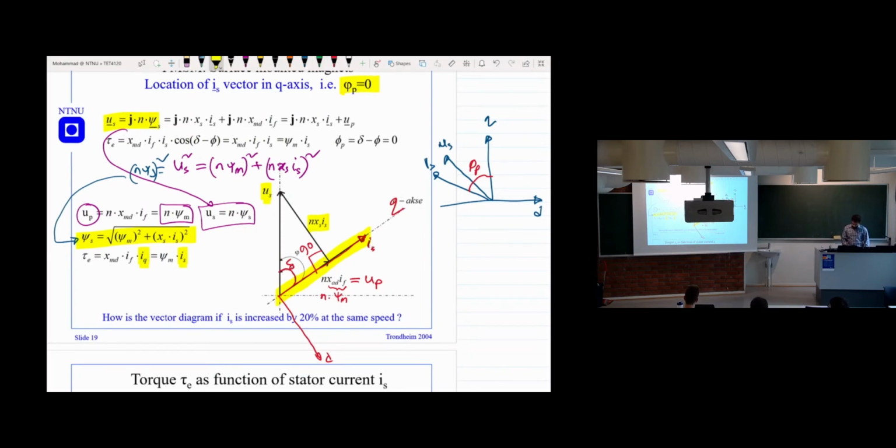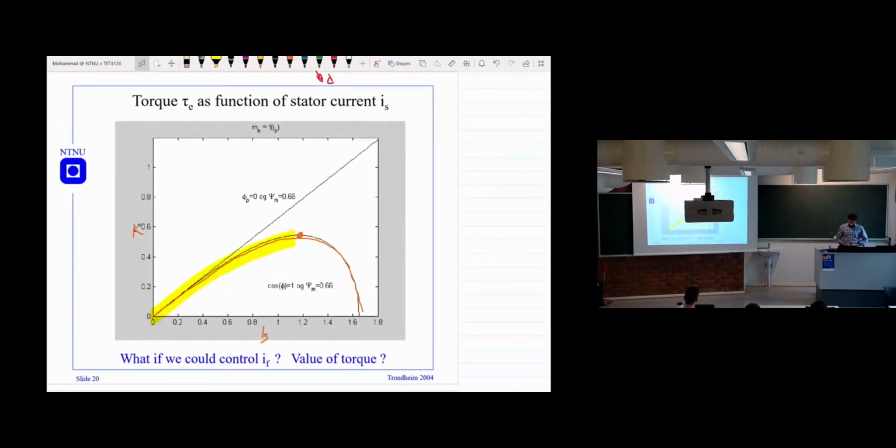So what this equation is saying is that the torque is now proportional to the current, since the magnetic flux is constant, and IS is the stator current. So this means I see a linear relationship. This means if you increase the current, it will increase the torque. Now if you plot this, you will see here, you increase the current, then it will increase the torque.